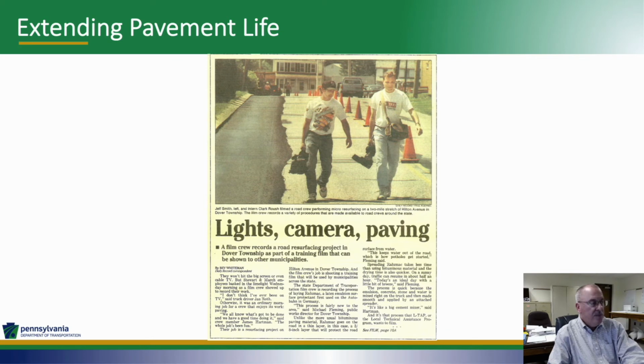When it comes to extending pavement life, York County and Dover Township for many years have utilized different ideas. The photo that you see here was from back in June of 1995, when Dover Township worked with LTAP and local contractor Stewart and Tate to create a training film on RALUMAC, a form of microsurfacing. Microsurfacing is still an approved PennDOT product that can be used today to extend your pavement life.